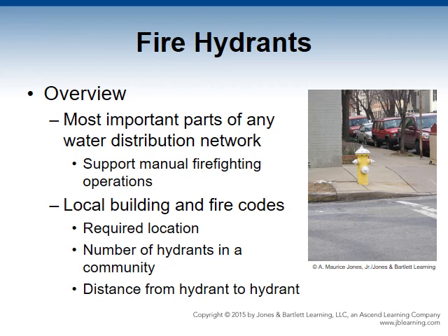Local building and fire codes establish the required location and the number of hydrants in a community. Most jurisdictions require hydrants where streets intersect and within 100 feet of a fire department connection. The distance from hydrant to hydrant must not exceed a maximum interval.